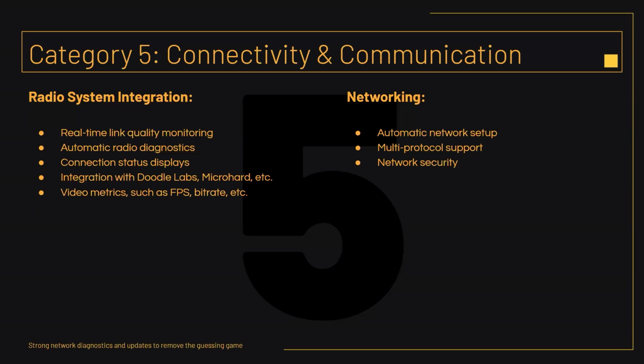So if for all your drones you use a certain type of radio and you want to support real-time network analysis or logging radio information, you might want to create something custom for that. There are many radios which don't even support RSSI over MAVLink. So you might want to add a custom RSSI display based on the way that you would hit the data pipeline for whatever radio you're using. But yeah, there's a lot of different things with this.